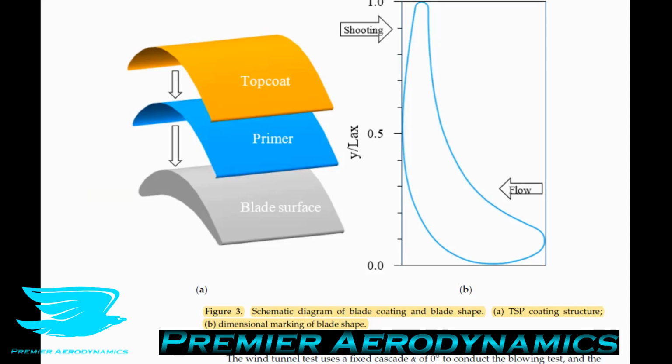I've talked about surface roughness before, and I'm going to do a few podcasts coming up about how surface roughness affects the flow over airfoils in particular. But it does make a big difference. If you have a rougher surface, you will get a very different boundary layer transition point to if you have a very smooth surface. So if you have an object and you want to be able to compare it to other objects, you should really try to control the surface roughness.